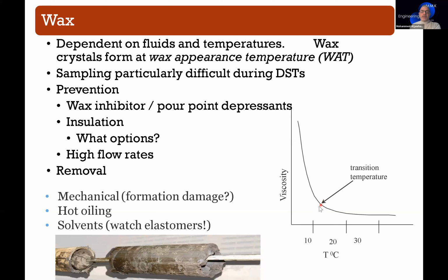We have to have a plan to remove this wax immediately from the well. Otherwise, you can see from this illustration the big impact of the wax inside the wellbore. It's almost taking the whole area, the volume of the pipe. So do we need to put in any heaters to remove this wax? Because increasing the temperature reduces the viscosity, and then we have a nice flow rate.